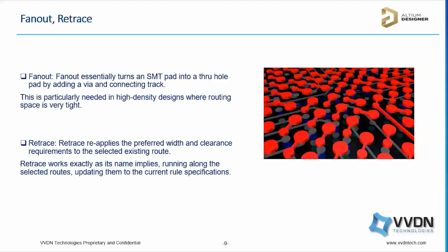Some important features in Altium are Fanout and Retrace. What is meant by Fanout? Fanout is a technique where short traces and wires are used to connect inner rows of pins on high pin count ICs. If you are doing Fanout for multiple pin ICs, Fanout can also route traces to a device with very closely spaced pins. This makes routing connections much easier by using Fanout.